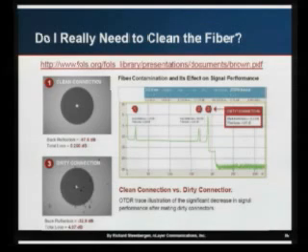Yeah, actually, the fiber does get dirty. There's a much more detailed presentation that you can go read if you want to see how the microscopes work and how to do the cleaning of the fiber. But there's an example where you see a really dirty connector at number 3, and that's just grime and dust and dirt in the colo. It gets in the way, it blocks the signal, and it can actually damage the connector to the point where you have to throw it away. If you have a piece of dirt in there and you get it embedded in the mating, it might actually damage the glass physically.